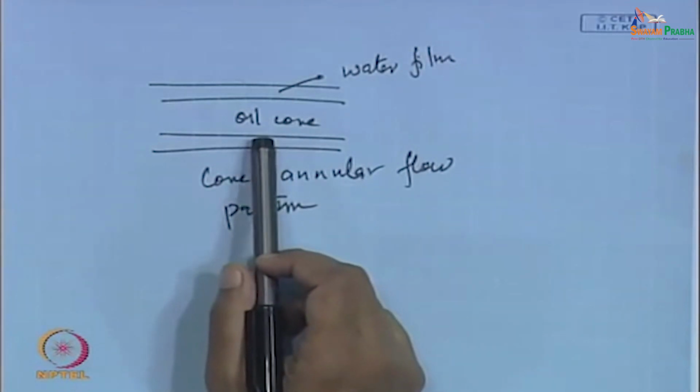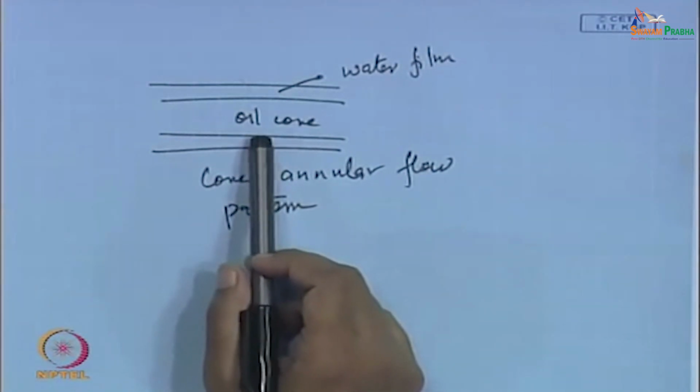So, therefore, as we go for more and more viscous cases, people have generally not found inverted dispersed flow for these highly viscous cases, and the core annular flow pattern occurs over a large range of flow velocities. Apart from core annular flow, we have some slugs and elongated bubbles, but mostly the flow pattern is core annular for all pipe orientations. So, even when we are working with liquid cases, the flow patterns vary depending upon the liquid properties. This is very important.